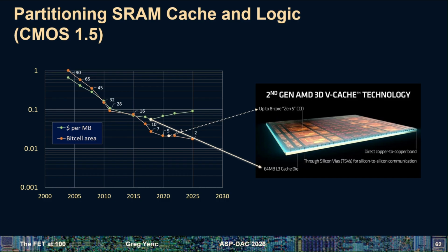And you save money just from the partitioning itself. And that pays for, conceptually, pays for the extra expense of the silicon, the through silicon vias, these TSVs, and the substrate. Those are not cheap, but pays for itself. In this case, AMD, for people buying this, they don't care much about the cost as the performance, but it pays a lot of dividends for other products.